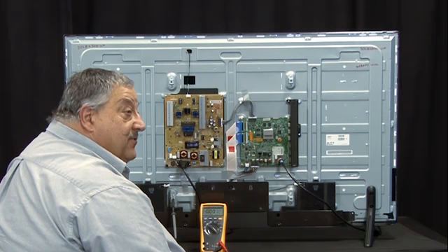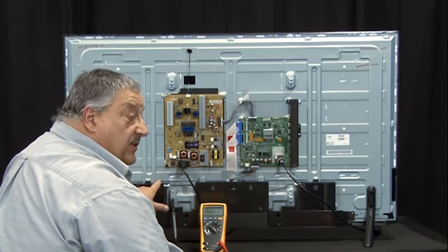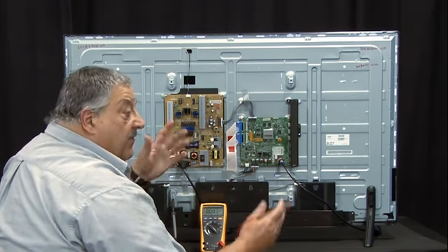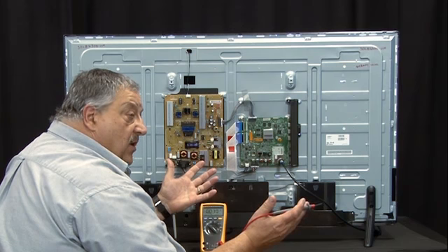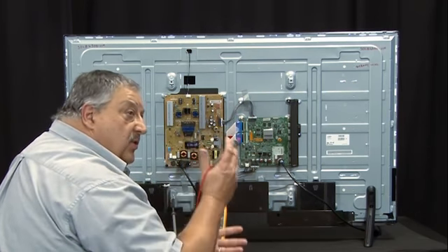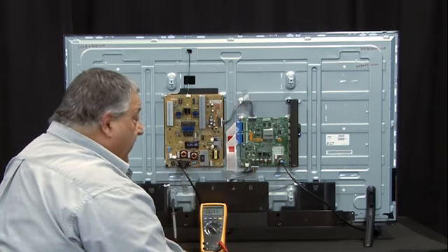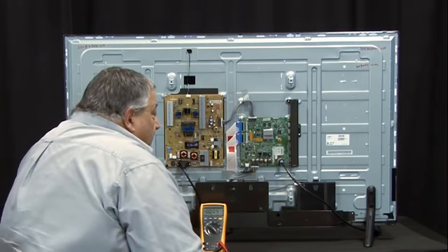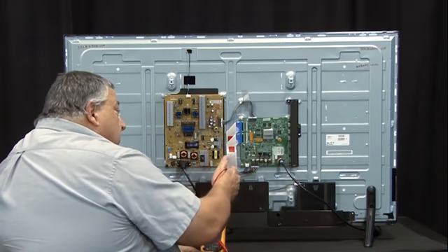Push-pull means that neither side of the speaker sits on ground potential. Therefore, you have 1/2 of the audio B+ on both legs, and then the amplifiers will push-pull the cone in and out to create the audio level. If you've got that audio, then you're in good shape.